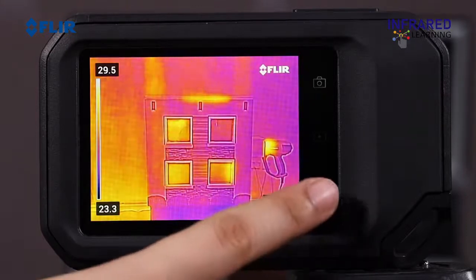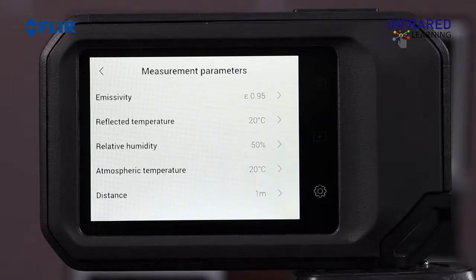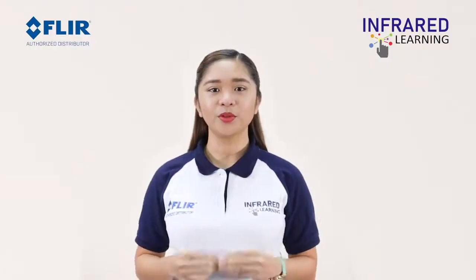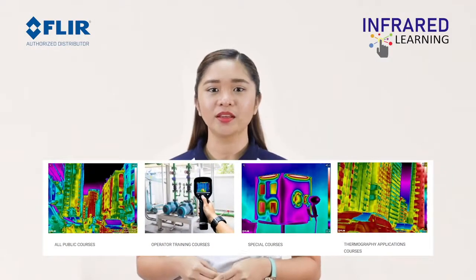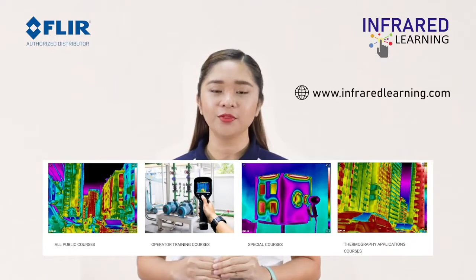You also need to adjust the measurement parameters such as the following: the emissivity, reflected temperature, relative humidity, atmospheric temperature, and distance. All 5 affect the accuracy of your measurements, especially the emissivity and reflected temperature. As such, these values should be set properly. With our specialized courses, you will understand the importance of each parameter and how to set them correctly. Be sure to check them out.